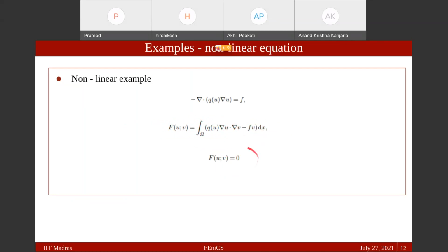With the command we will be seeing in the next slide. If we want to solve this in a conventional nonlinear FEM way, we take it as a residual. We minimize this residual with respect to u by writing a Taylor series expansion, and then we construct a tangent stiffness matrix and everything. All that computation we have to do manually when we code it in MATLAB or Fortran. But here we need not. It just segregates itself out.